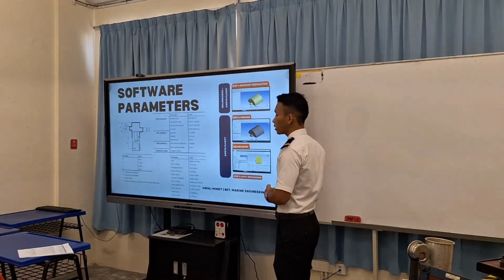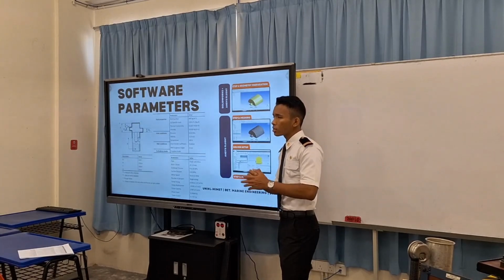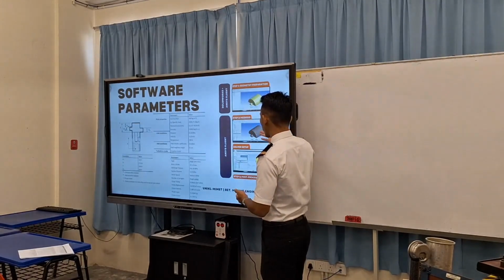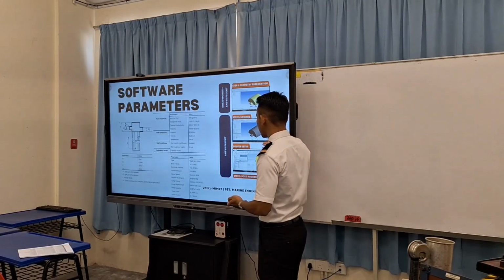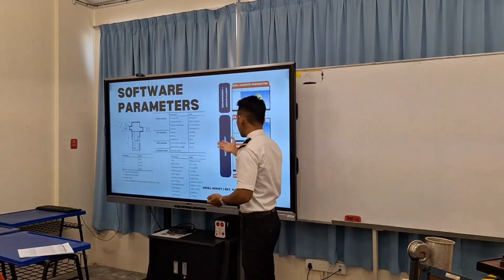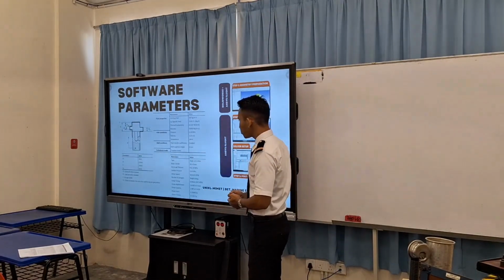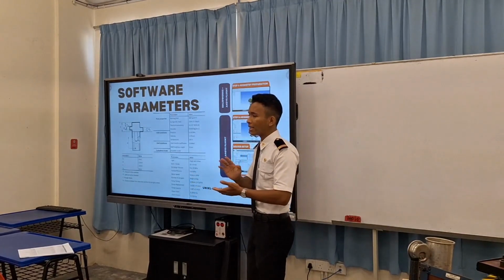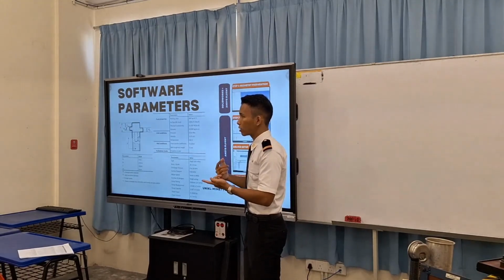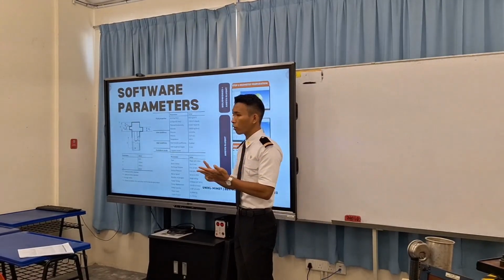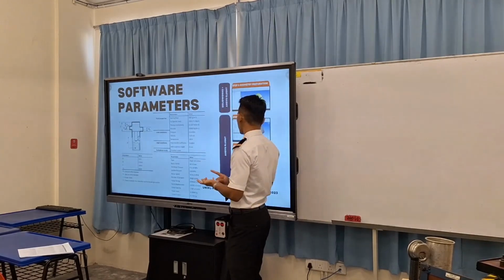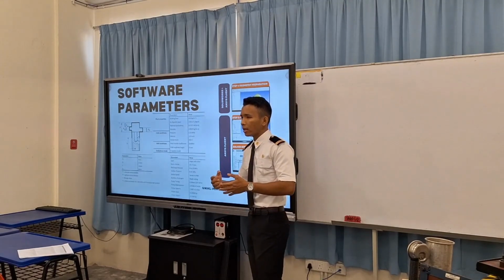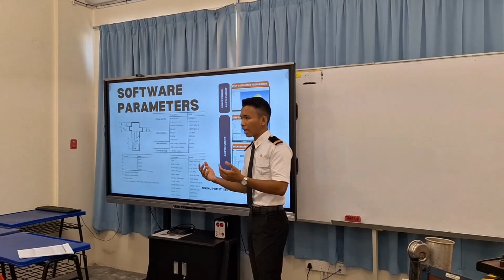The first one is geometric preparation using SolidWorks software, and then extracting into the sequence of step 2, where I will start the machine and solver setup. I include all these parameters into the setup, and these parameters are taken from the analysis of journals of past research and the manuals from fluid manual books. And the last step is post-processing, where I take the animation and extract the data.